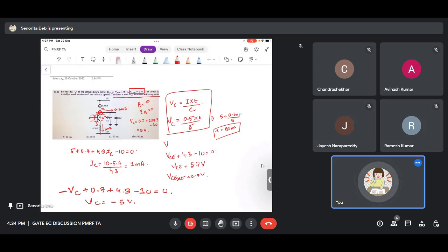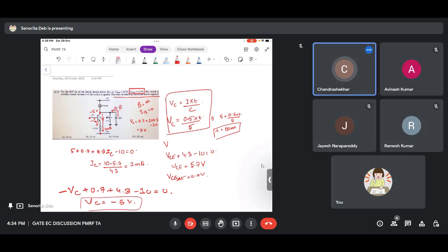Yeah, sorry. So I have taken the direction of current as wrong. So that's why. Okay. Yeah, good point, ma'am. Thank you. So this will be minus 5 volts here. Okay. VC is minus 5 and the current direction is like this. So 0.5 from this, and therefore 1 milliampere goes on here. And 0.5 plus 0.5, then 1 milliampere. Okay. So even if you take VC negative here, the minus sign with the current will cancel out. Okay, so T is 50 milliseconds. Thank you for pointing out.